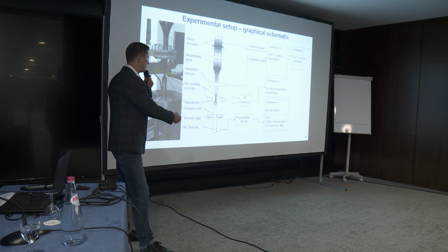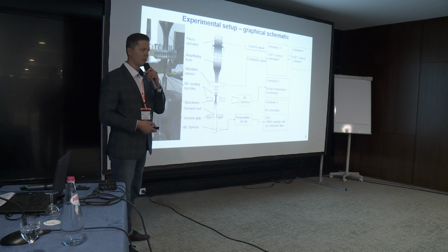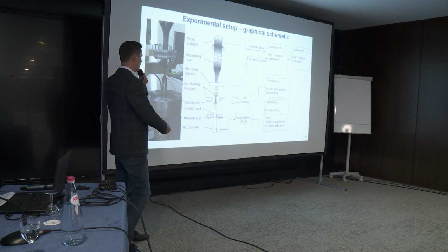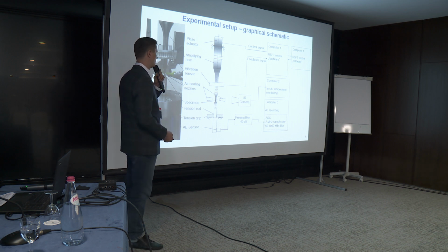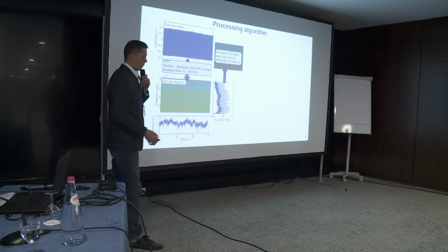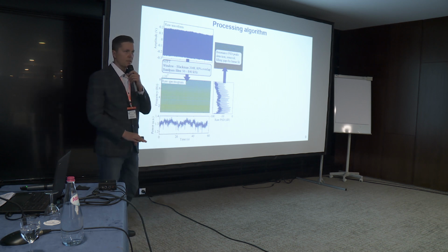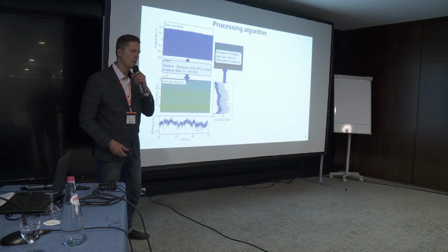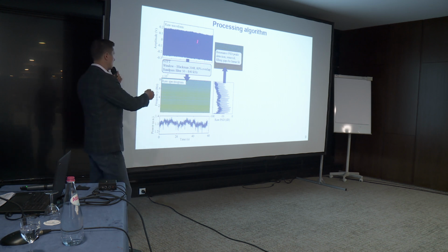We use an infrared camera to monitor the temperature, so the specimen remains around 20 degrees. And we use an acoustic emission sensor, broadband, with a 2 megahertz sample rate, and a filter. We record the acoustic emission in a threshold-less mode, so we record everything. It's just a stream, and it looks like this.